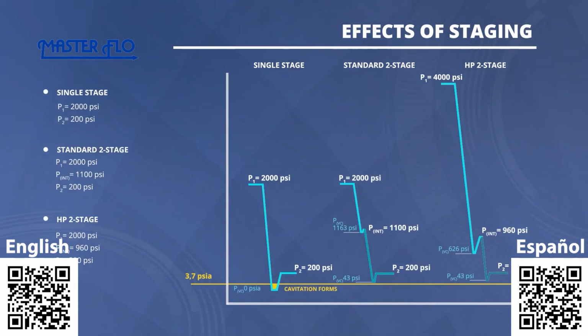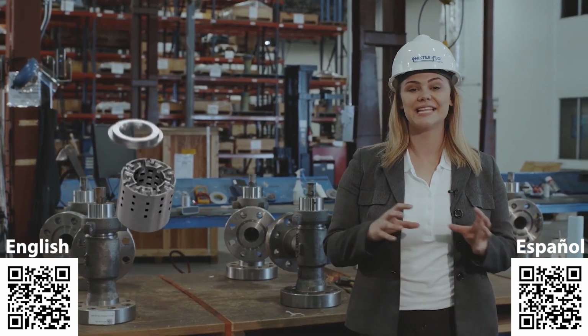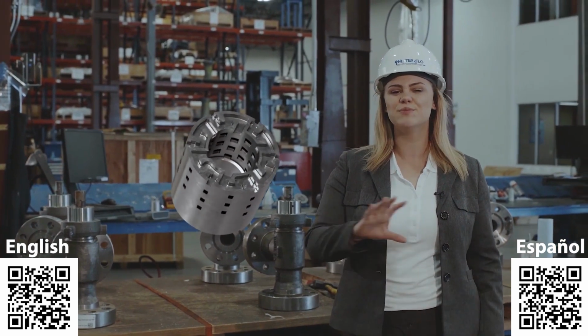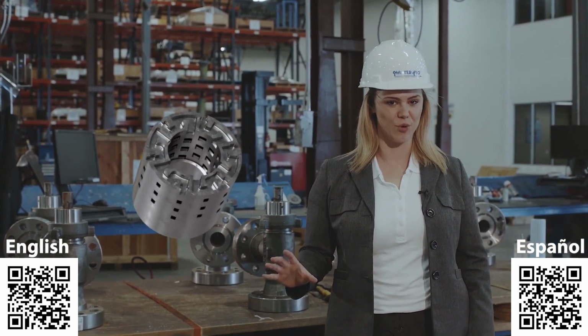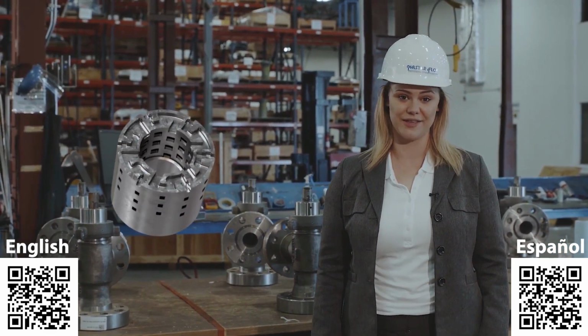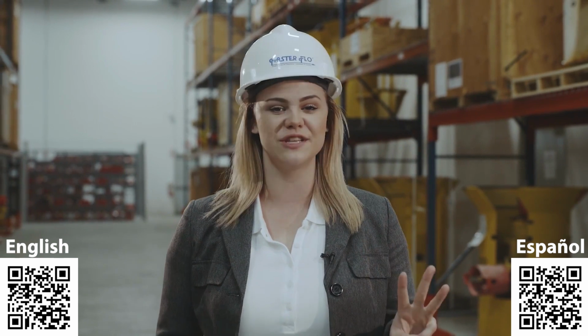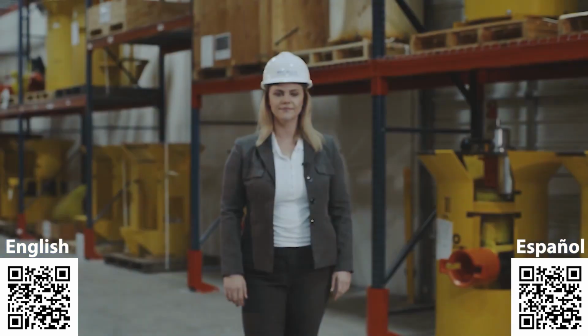When more than two stages are needed, a labyrinth style trim is employed. It features an internal plug and a labyrinth cage that allows a smooth transition between cage ports. It also controls the velocity throughout the labyrinth. These trims are available for liquid, gas, and multi-phase applications.